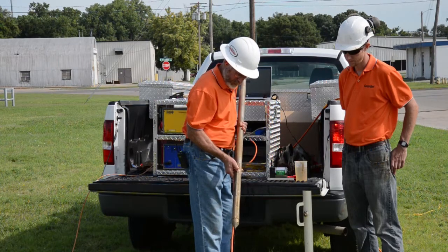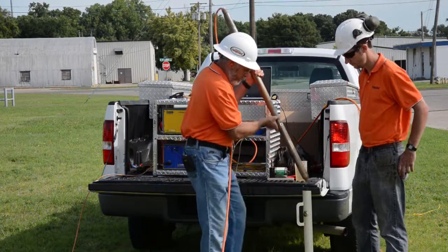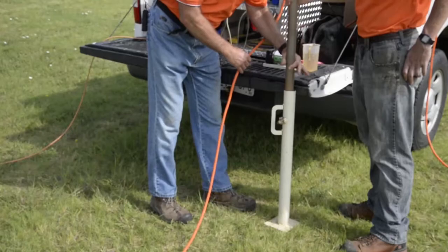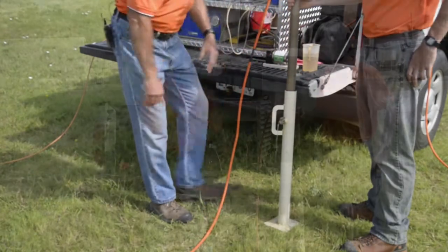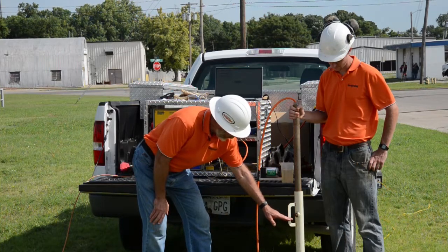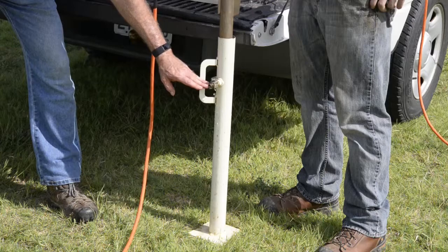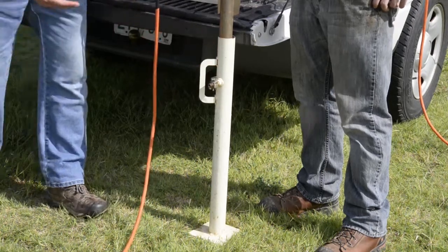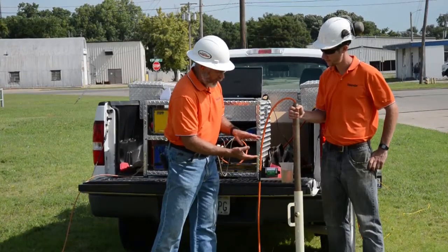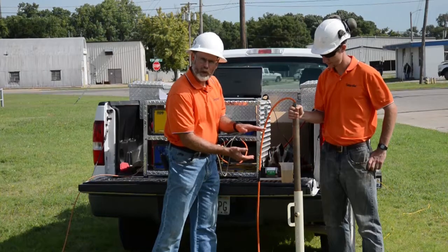So it seems we have pretty good response. We'll go ahead and put this guy in the reference tube, and you can see the valve here is open, water flowing out, and the top of the reference tube is 6 inches above the valve. So what we'll do, we'll measure pressure at bottom with flow and the top with flow, and then we'll do a pressure measurement without flow. That will be our real QA test.